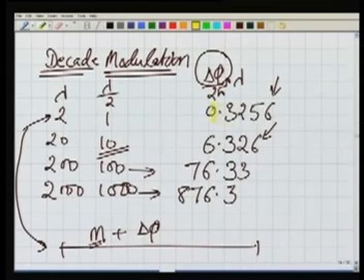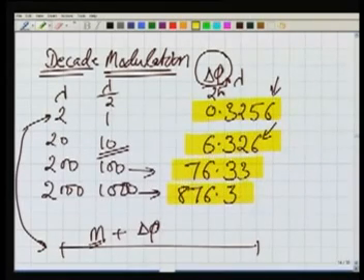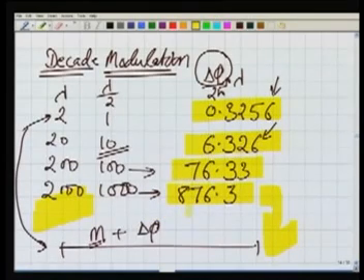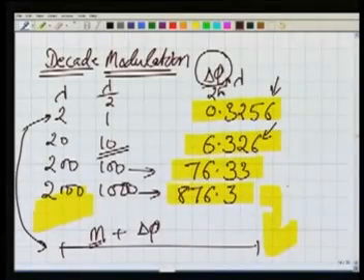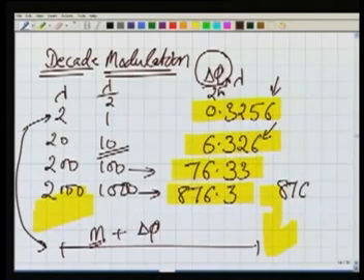Now all these measurements, what I am writing here, we are getting because of the measurement of the phase only. Now if you increase your value of lambda, you notice that there is no change in this distance, or a very minute change. It will not change as it has been changing so far. So that's the point where we stop, and here we can say easily that our distance should be, I will write the full distance, 876.3256.